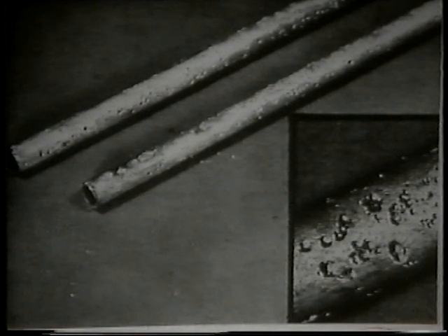If we allow stagnant seawater to sit in the piping system, solids in the pipe can deposit out on the pipeline, and we get concentration cells started, and we see pits and concentrated severe corrosion underneath those deposits. There's a tremendous wealth of data on corrosion in marine environments because it's such an important environment to us for shipping, obviously, Navy, and so forth.